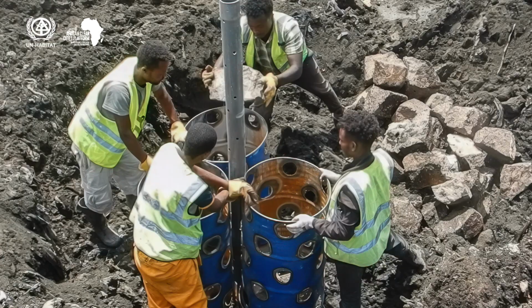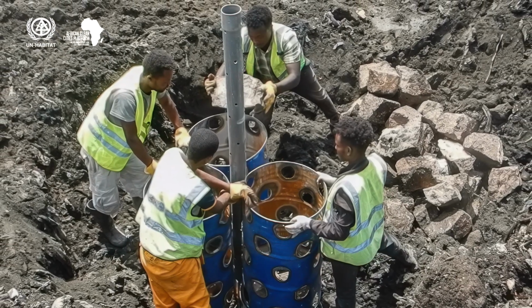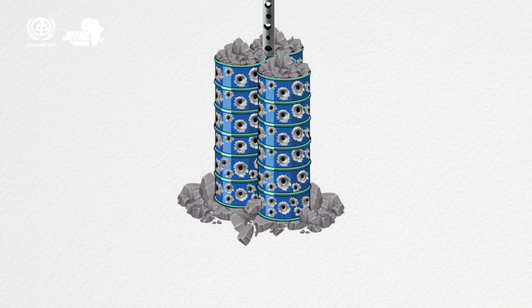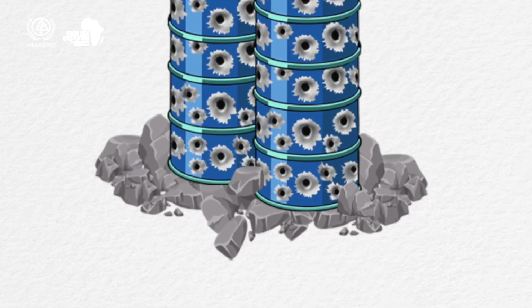There is a possibility that methane or other harmful gases has already generated inside and the hole might be filled with harmful gases. We recommend that digging should be limited to the depth where workers can always reach fresh air. Here, the venting system can be secured by placing it on some cobblestones, which should also be arranged to provide side support. It may be necessary to extend the height of the venting system as the landfill fills up.